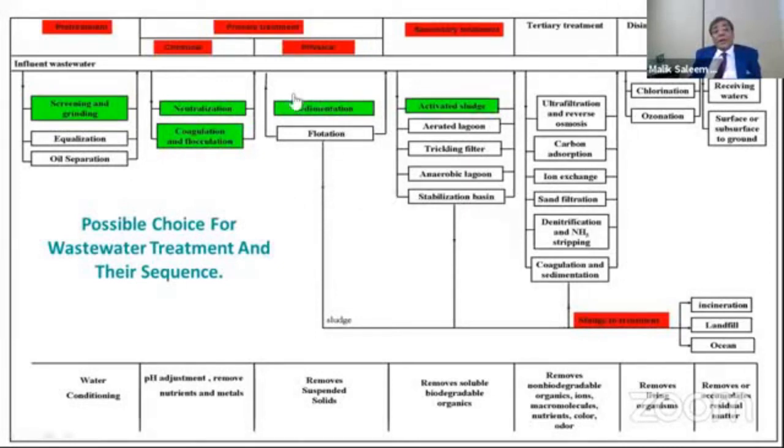These are the pre-treatment conditions for the biological phase of the treatment, because we will have to meet certain conditions where the living organisms like bacteria will grow and make the activated sludge. If the temperature is more than 40 degrees, and the pH is greater than 8.5 or acidic below 6.5, the bacteria will not grow, and there will be no activated sludge formation, and it will not digest our contaminants which are contributing to BOD and COD.